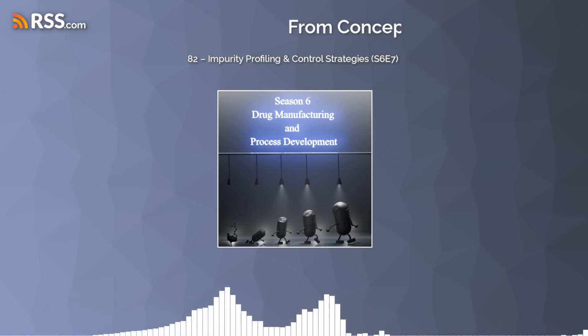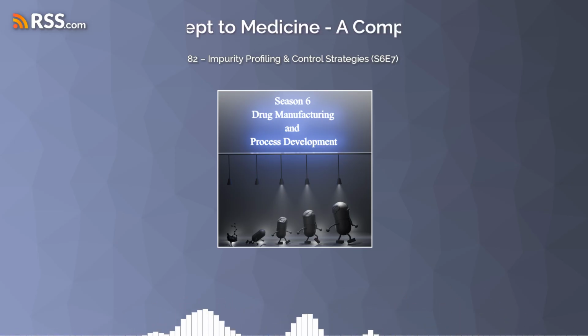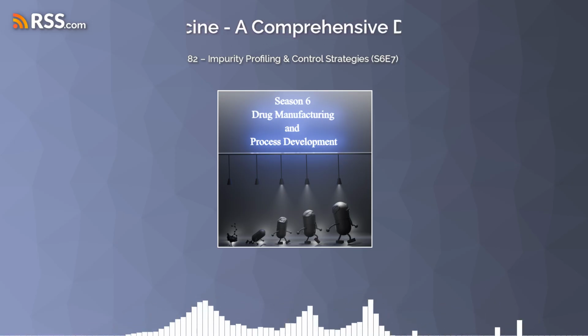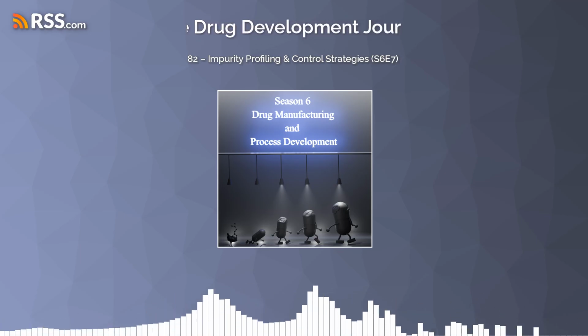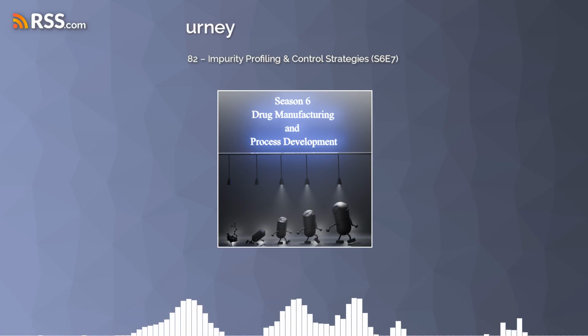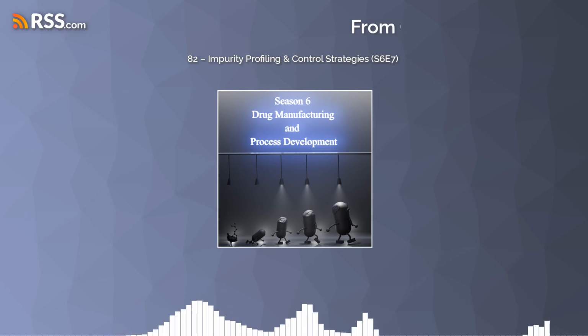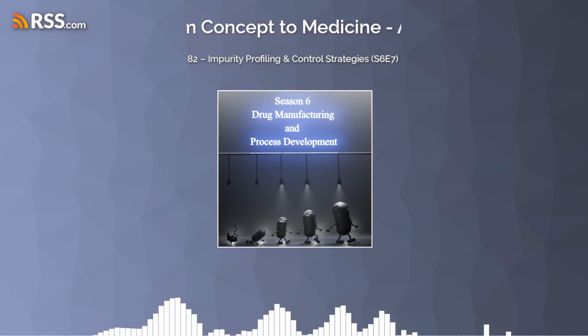Exactly. And crystallization is another key player in this control game. It's often thought of as just getting the drug into a solid form, those nice little crystals you see. But it's actually a really powerful way to purify things, too. There was this really cool example in one of the sources about how they use different solvents like IPAC and methanol to improve the optical purity of a salt form.